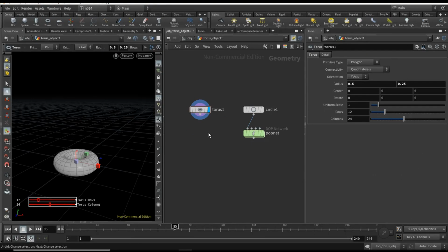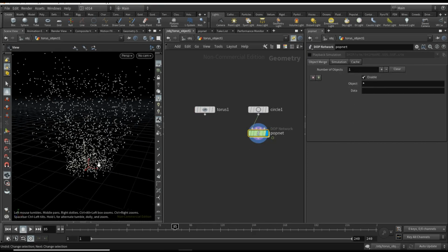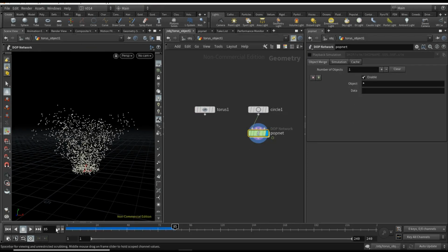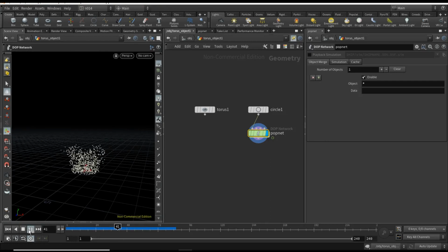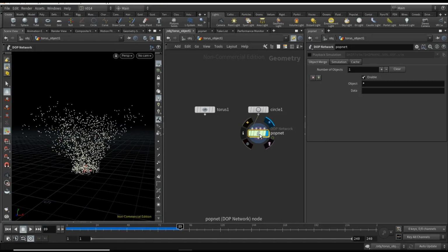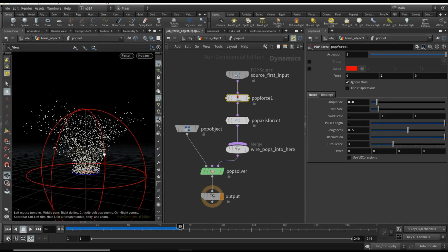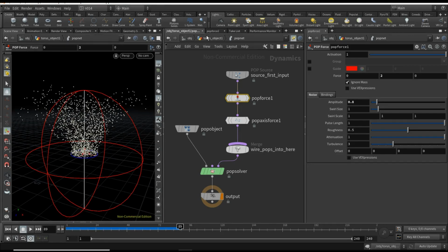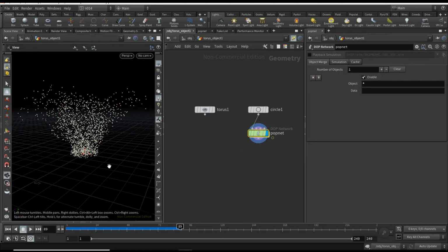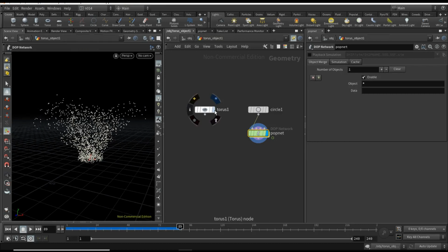Now in this case we wish to source smoke from an object, say torus, but velocity is to be derived from particle animation happening in a different chain. Now this is a simple particle simulation with an upward force applied and a small orbit force as well, so the particles are revolving around y-axis. Let's move one level up and create the necessary structure for density volume.